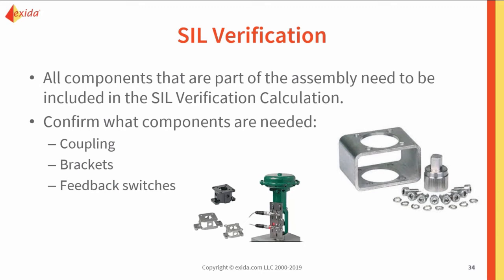Once again, your safety system in your building is going to be only as good as its weakest link. You could have the top of the line, the sports car, the best of the best valve and the best of the best actuator. But if you mount them together with brackets that are just sheet metal that breaks, and the valve and actuator fall apart from each other, it doesn't matter how great they would be. It won't do its job. So when you do the SIL verification, all components need to be included.